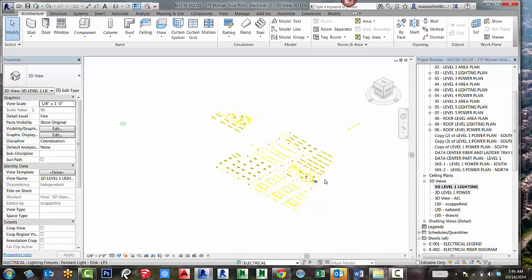Because they used a linked model system and a work sharing system, all of their models are automatically linked, and we're just separating it, basically slicing and dicing the model for ease of use and for the subs, and then everything gets put back together basically in Navisworks. So everything will come in at the right elevation, unless something was drawn on the floor, and then it would show up at 0, 0 or on the floor of that level. But for these files, they should show up because the architect and engineers work together in a work sharing environment.